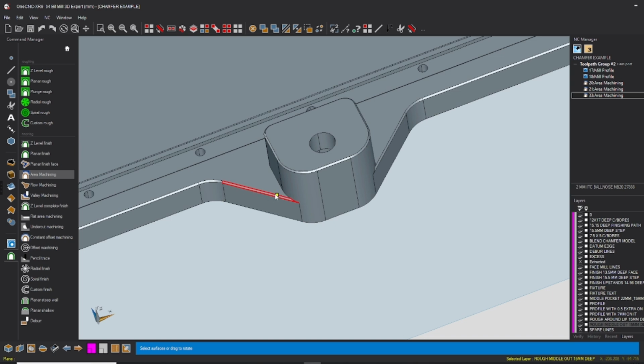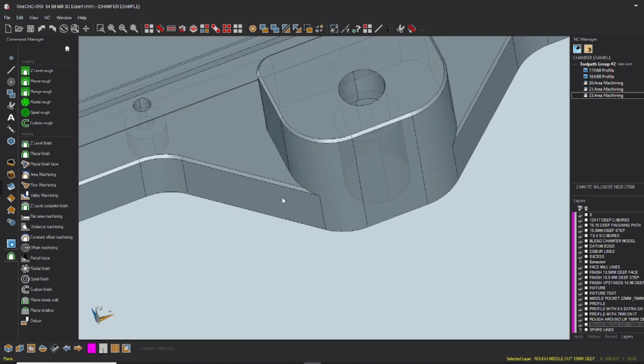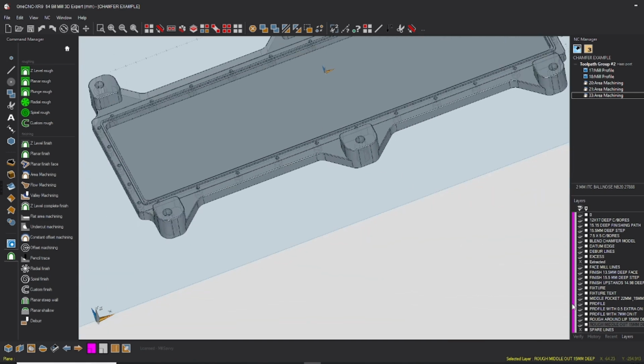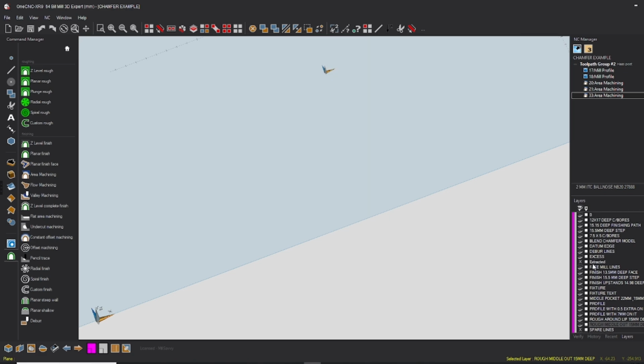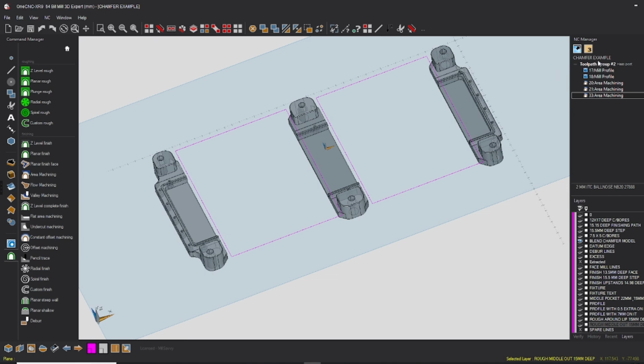You don't want to waste time, you know, sending your ball nose up and down here, blending this chamfering with something that's already been done. You're not streamlining your process there. You may as well just do what I did, extrude cut, and do the one bit that you can't reach with your spot drill or your chamfer or whatever you're using. That's why I did that. It's about keeping that runtime down, keep it efficient. Don't waste time cutting fresh air.